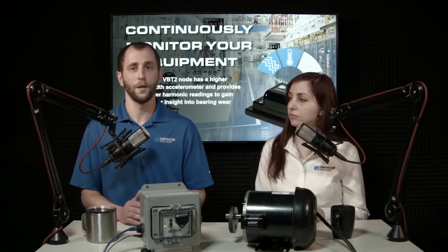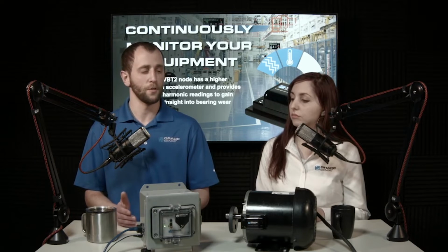The hard thing with those, though, is when you get a temperature increase or current draw increase, that's going to be later in the cycle. So you don't have as much time between when you see it and when it fails. If you have a temperature increase, that might be very close to failure. You wouldn't have the time to get in the part you need, get it on your maintenance plan, and get your PM scheduled. So vibration monitoring is one of the key techniques to give you more heads up before something happens.